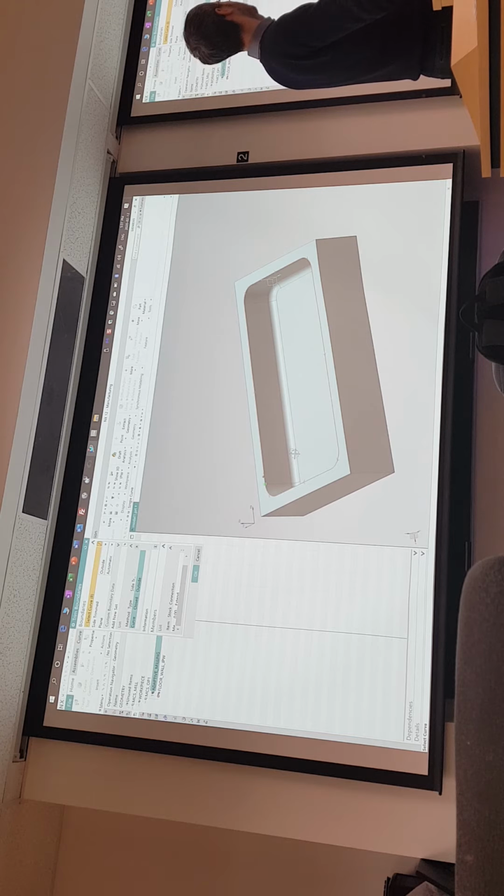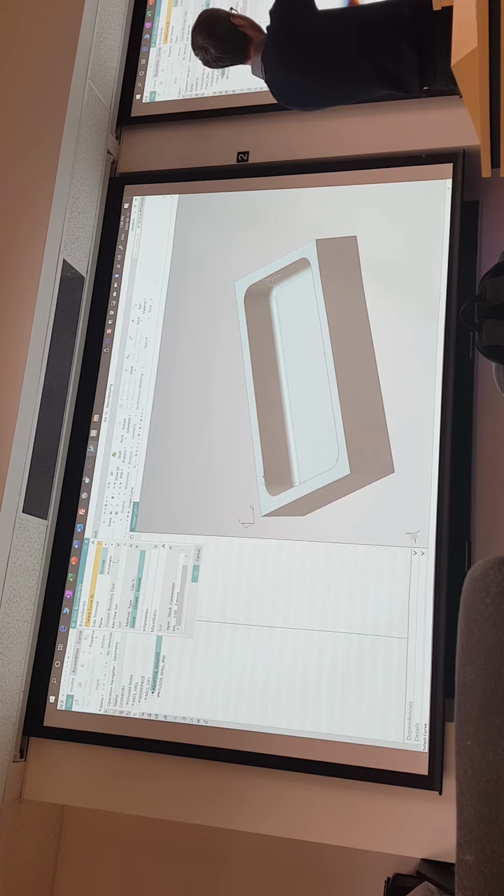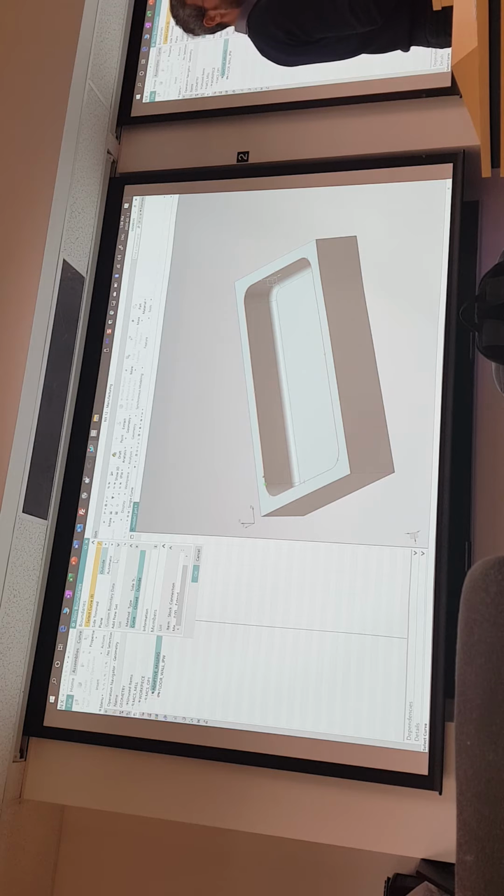You're telling it that even though I have raw material on the outside of the part, I want to cut in this area. And don't ask me why I pick outside or inside. For me, inside is inside the pocket and outside is outside, but in this case, outside is inside. So sometimes it says there's no material to cut, just flip this from side trim from inside to outside or the other way around.